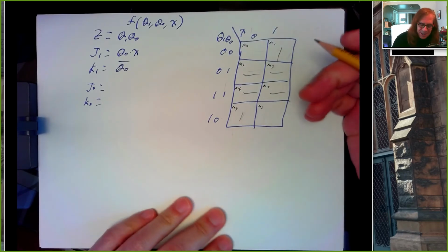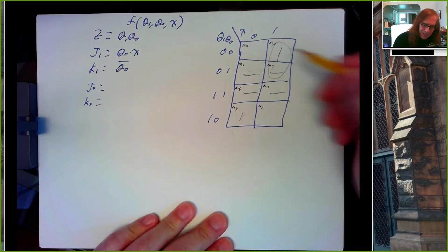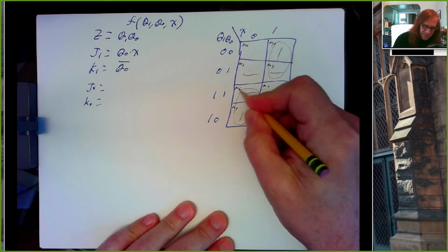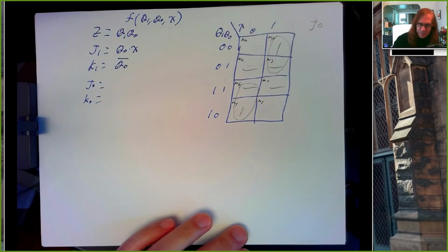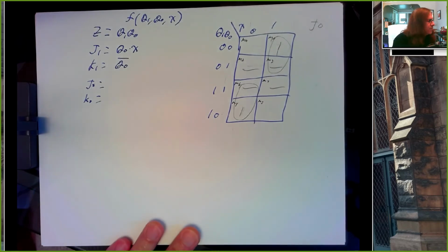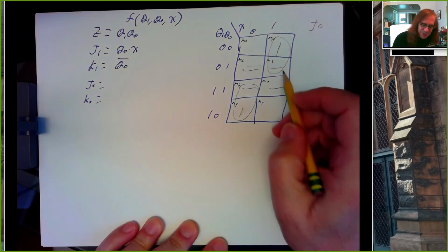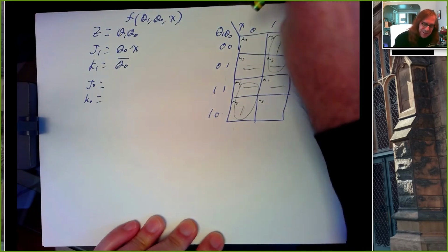And we can't do as much as I'd like to do here, but we can certainly cover that one with a 2x1, and we can cover this one with a 2x1. Anybody see a better cover we could use? I think that's probably the best we can get. I mean, you could circle the 4 don't cares, but why would you do that? Yeah, we could circle that too, and that would be a nice small expression, but since we don't care about it, we won't.